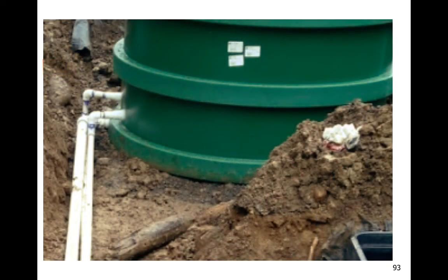Now, when we do the plumbing, it's important to note that when these basins are made, there's three ribs. The top two ribs, the outside edges, are pretty much straight up and down. The bottom rib, because of the way it cools, kind of tilts in just a little bit. So when they weld in our fittings for our tank adapters, that very bottom fitting is actually pointed up ever so slightly. So it's important that we have a very short piece of pipe, maybe even use a street L, but come out with the first fitting being an elbow.